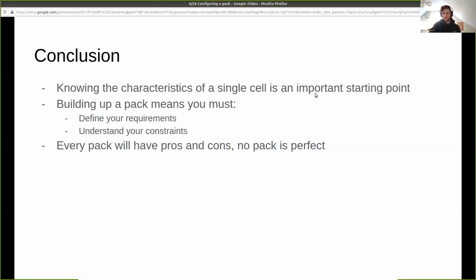But the reason why we were using pouch cells before is just because when you have a lot fewer cells, it's a lot easier. There's a lot less repeatability when it comes to manufacturing, and they're a lot safer, in case you were wondering. Yeah, most commercial vehicles that care about how fast it is to build a pack use pouch cells or prismatic cells, for exactly the reason Kasha just said.